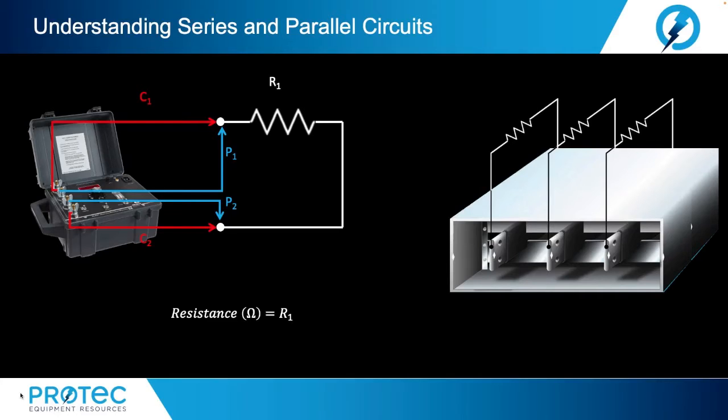Now, a DLRO, ductor, or micro-ohm meter being a 4-terminal measurement, the instrument is metering the output current. Therefore, if the test leads were to change length, this does not become a factor in the measurement. The current flowing through the entire loop is always a measured current in this style of instrument.